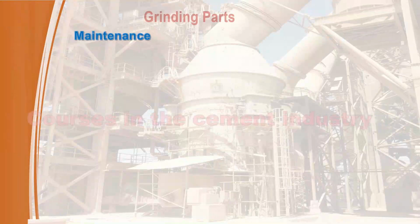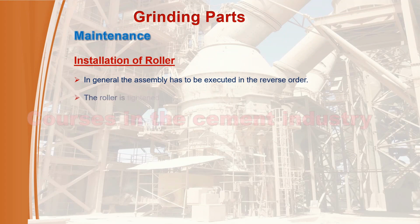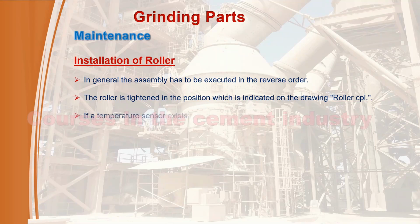Maintenance 4. Grinding parts. Installation of roller. 1. In general, the assembly has to be executed in the reverse order. 2. The roller is tightened in the position which is indicated on the drawing roller. 3. If a temperature sensor exists, see operating instructions, roller temperature monitoring.